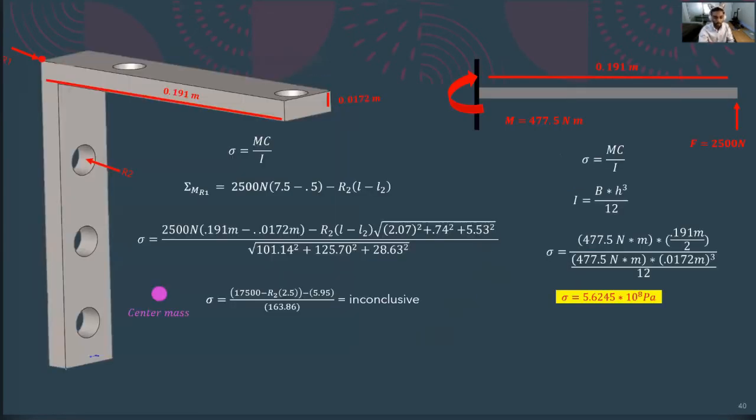Here we can see the approach taken on the right uses two reaction forces to determine the magnitude of stress in the bracket. However, this method would leave us with an over-constrained component. The method on the right simplifies the bracket to a simpler beam load, which when calculated gives us a magnitude of stress that would again lead to yielding, verifying that the SOLIDWORKS FEA analysis is correct.